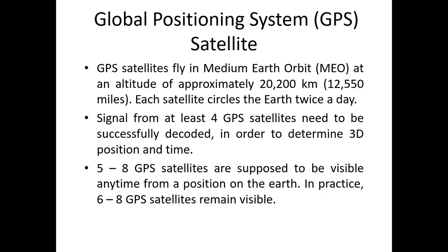Now, at the receiving end, using correlation, you can determine where the whole sequence is located. The sequence will arrive at the receiver one after another. You're receiving the signal, so it's a bit stream. So you are receiving the bits in the sequence one after another. So using correlation, you can find out where the sequence starts, where it ends, which position you are receiving right now.